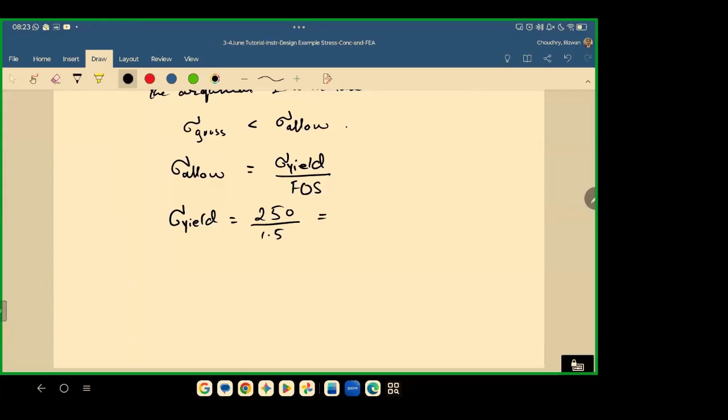Sorry, it's taking a few minutes to start. I will change the unit system as well. Now if I go onto the material option here, I can go into edit material like I did the other day, and I can search for ASTM A36.